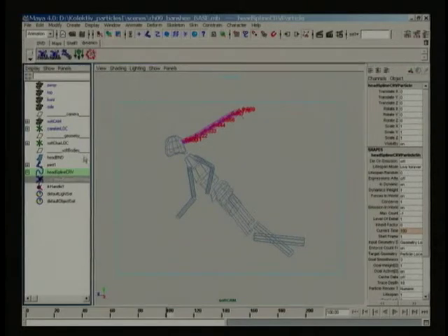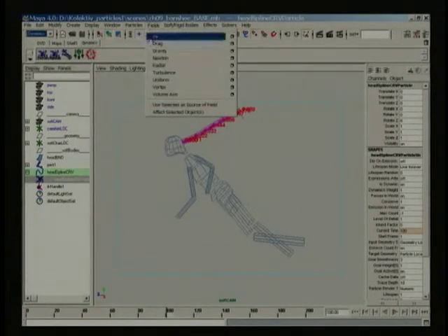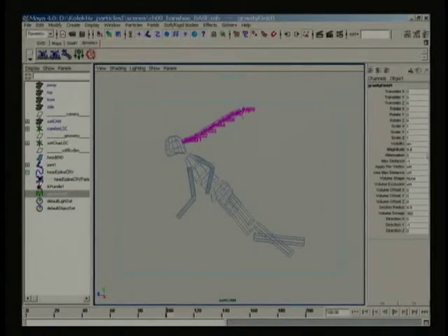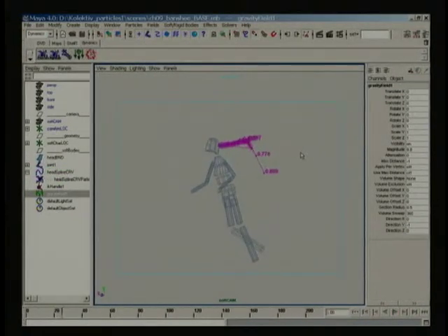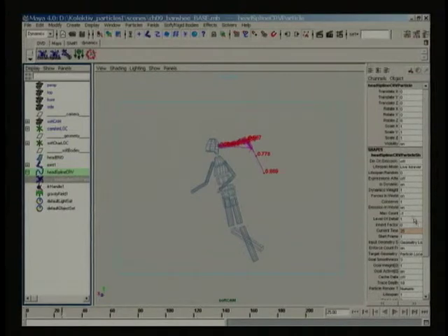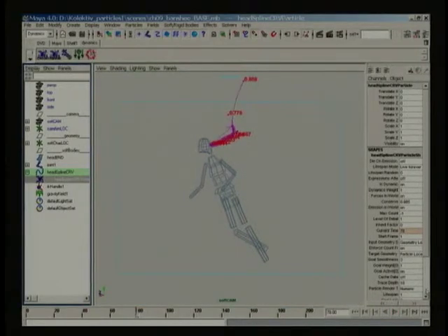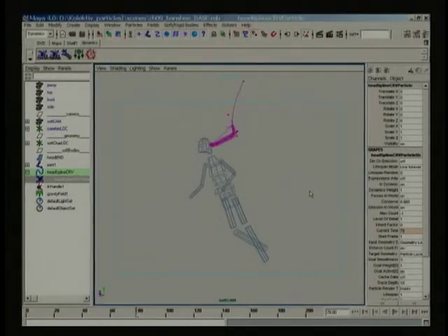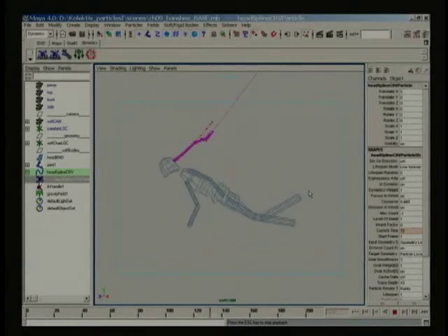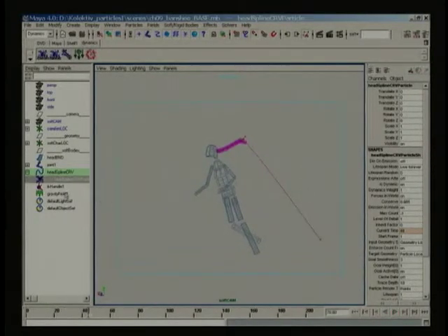I'll add some gravity to the softbody particles and turn their conserve attribute down to 0.95. It's important to always reduce your conserve attribute from the default value of 1. Most of the time, you'll want your particles to lose a bit of their energy as they move around. Otherwise, you'll spend most of your time trying to chase them down with various fields to control their movement. I've found that conserve values in the range of 0.9 to 0.985 work well for most simulations.